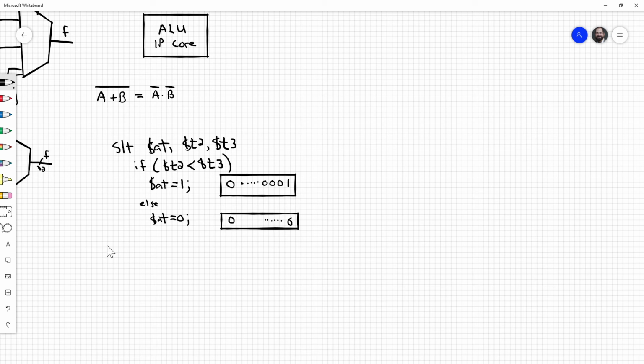So in terms of implementing this set less than operand, this is probably closer to the 281 approach here. We have to recognize that for all of those most significant bits, from bit 31 down to bit 1, I could have drawn another 0 here to make it more equivalent. For bit 31 down to bit 1, the result of a set less than instruction, or the operand in our operation in our ALU, is always 0.